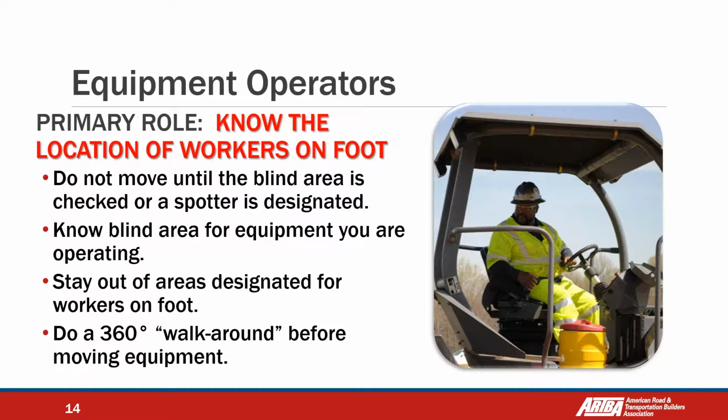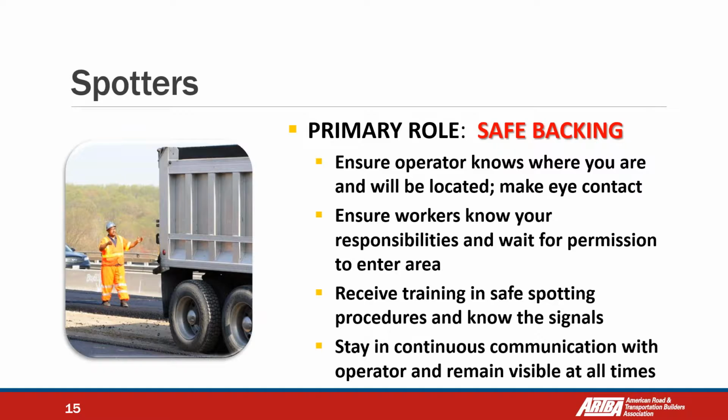We watched yesterday in the presentation that every vehicle has different blind spots. They are not the same. So whenever they are using a different kind of equipment, they need to be aware of the difference in the blind spots. Stay out of areas designated for workers on foot. Just comply with the internal traffic control plan. Don't mess around in areas only for workers on foot. Do a 360 degree walk around before moving equipment. We were talking about it yesterday too. So some basic instruction for operators.